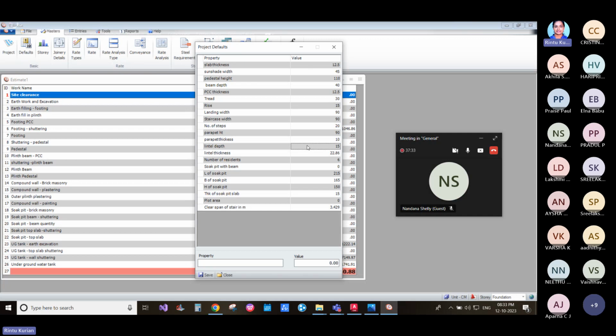It is a calculation done by a structural engineer, and the same will be given while giving the structural drawings. You can refer to the same for the value. And for the time being, you may assume it to be 15, which is usually the value taken for normal windows of smaller width. Then you can go for the lintel thickness.